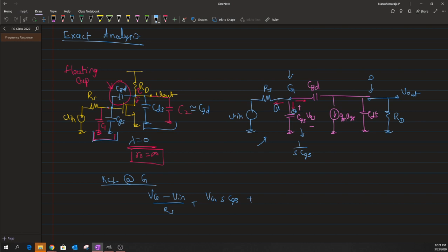And again, there is a current flow between the gate and the drain through the capacitance CGD, so I first write the potential difference across the gate and the drain, which is Vg minus Vout, divided by the impedance posed by the capacitor CGD, which is s times CGD. All of these currents add up to 0. That is how I bring down this KCL.